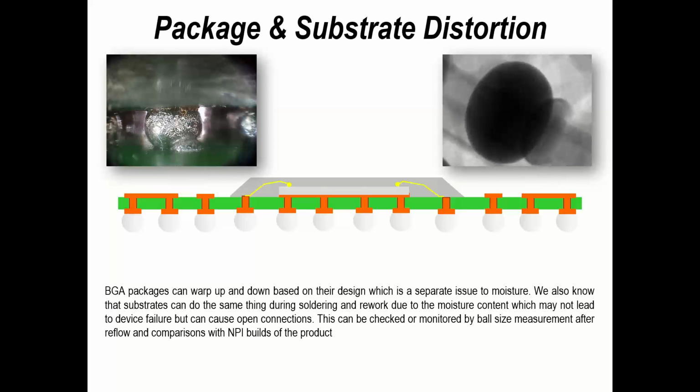So if you get this phenomena take place on a board by movement, flexure, expansion, call it what you will, this can lead to one of the soldering defects that a number of companies have to suffer sometimes, which is a head-on pillow or head-in pillow. So what you can see here, X-ray and an optical photograph taken by myself, which shows an open solder joint.